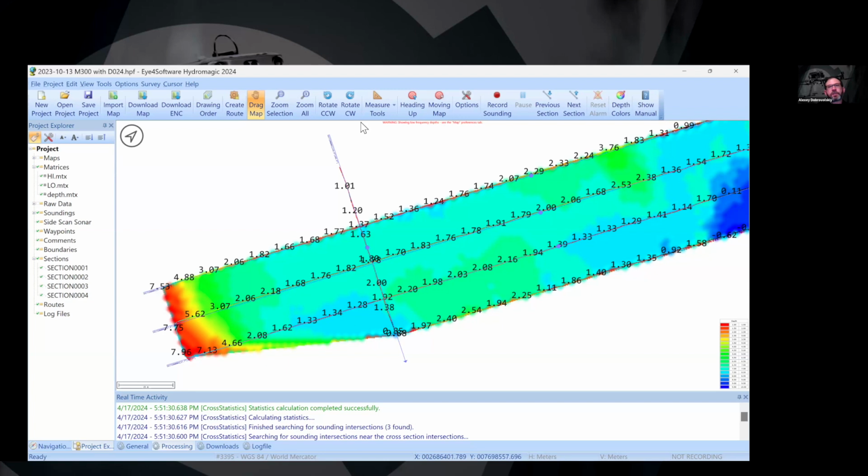For such cases, we can recommend a low-frequency GPR system. We also supply such systems. They work not bad in fresh water, if the water has low electrical conductivity. But in most cases, you can use the echo sounder attached to the drone. It is actually a benefit of the technology. It is very robust. If you are able to put the echo sounder in the water and it will be more or less vertical, you will get measurements.